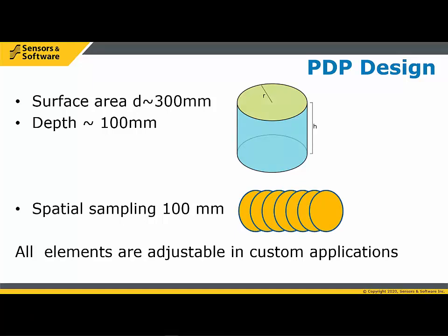We had a good example of that where we were on paved asphalt, and then there was a section of asphalt which was the same material, but the surface had been essentially ground down and it had a surface roughness of about maybe a centimeter in height and maybe a centimeter across, and that scattering from that roughness reduced the amplitude by about 20%. Even though it's the same material, the reflection or amplitude went down by about 20%. We've modeled this stuff and you can see exactly that. There's a lot of variability introduced by surface roughness.